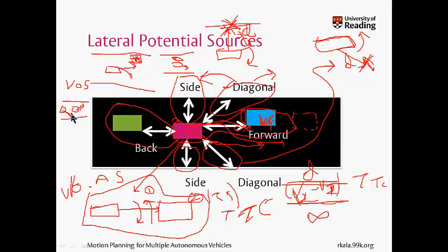If this turns right, I'll turn left. If this turns left, I'll turn right. So it'll basically be the converse of the vehicle avoidance strategy of this vehicle, and the time to collision will give me the magnitude. If time to collision is very low, I need to turn very high. So basically we've seen that there were always two things, direction and magnitude, except for these two cases.